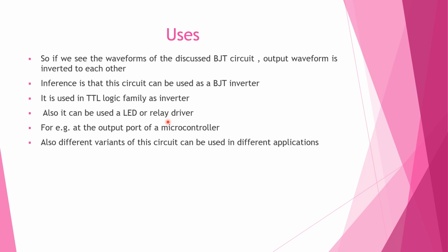So for example, the output port of a microcontroller cannot source that much current. Usually it will be maximum some 100 microampere. So if we give 100 microampere at the base terminal, it can drive some 10 milliampere, taking 10 milliampere current at the collector terminal.